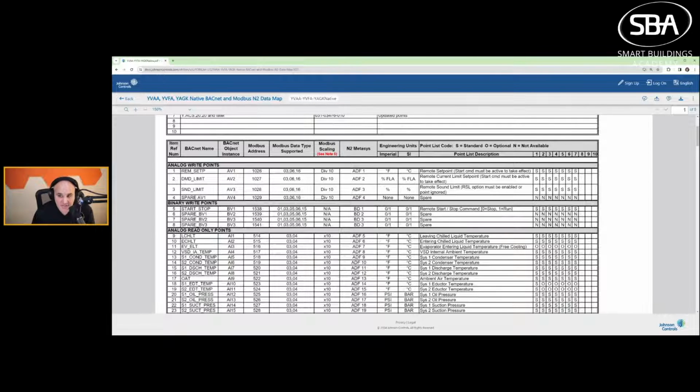Since you know 0 is stop and 1 is run, what would you want to do? You would want to go to your integrated Boolean or binary value, go into your unit types or your facets, and set the false, which is 0, because in Boolean 0 is false, to stop, and set 1 to run. That way it's easier for the person looking at this. You can see it's a little confusing, right? Remote start stop, but it's actually stop run, and this is called start stop. So you want to make sure this matches the actual unit types or facets as much as possible.